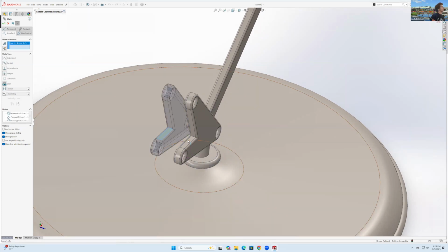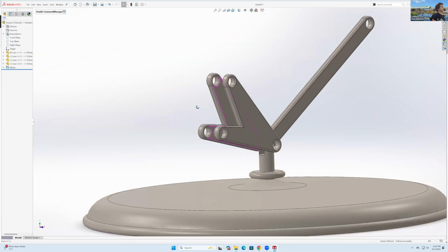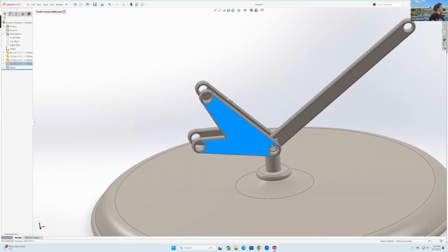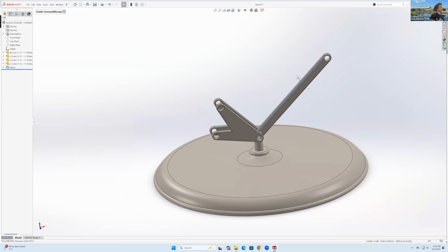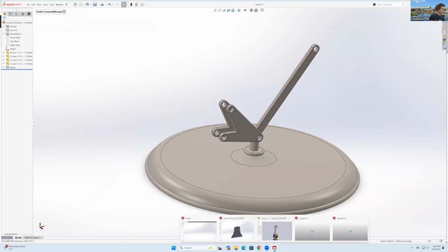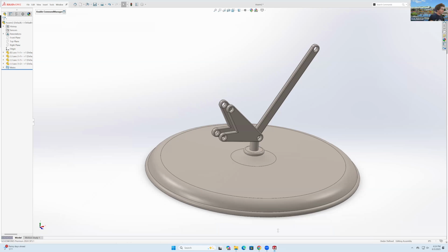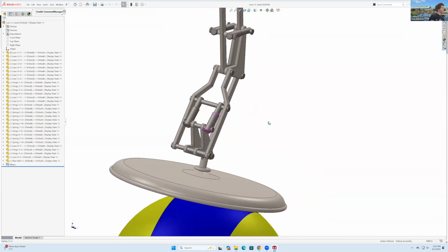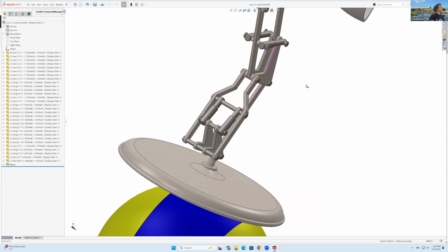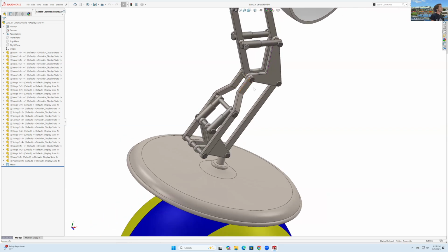And then I'm gonna click on these 2 faces and I make them coincident, I can make them parallel. So what this does is that now these guys are constrained in space to always be rotating together like that. So we got these 2. So I'll have a couple more and then I'll start walking around. I'll challenge you to build it yourselves. So let's add these 2 right here, and then I'll add those 2 sideways.